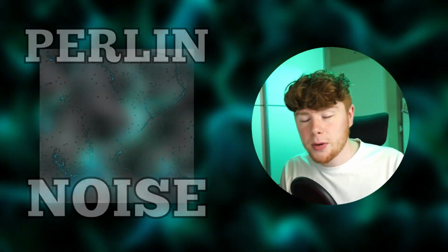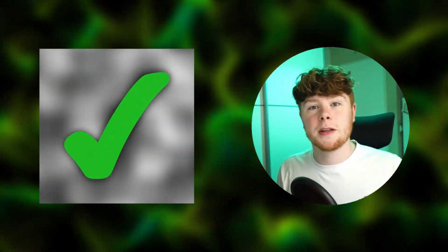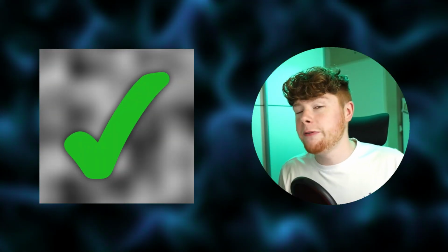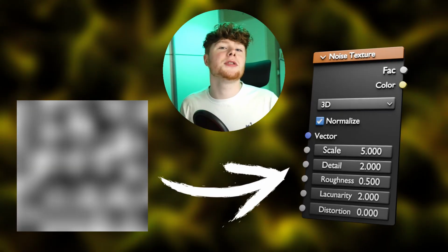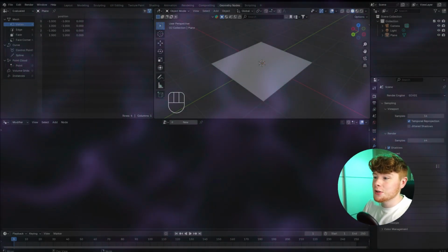Flow fields are these cool looking patterns that you get when you simulate the movement of points over some noise. In particular, this noise is called Perlin noise. And Perlin noise, as you can see, is not just a random value per pixel. Instead, the random value of each pixel is dependent on the random value of each other pixel. And in Blender, the noise texture node actually uses this exact same technique. So that's exactly what we are going to use in this tutorial.